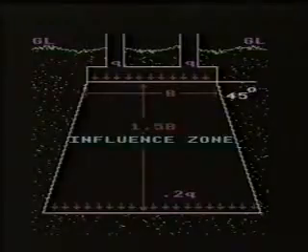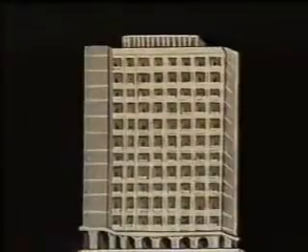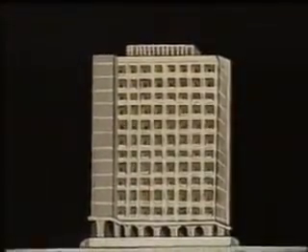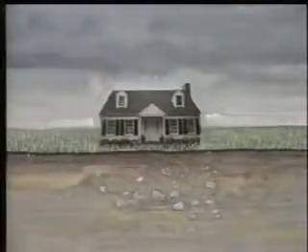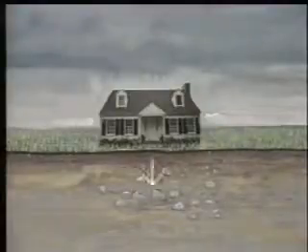Samples should be collected from the influence zone, which extends up to a depth of 1.5 times the width of foundation. For compact building sites, say up to an extent of 4,000 square meters or so, samples are collected by making boreholes, one in each corner and one at the center. For small buildings, a single borehole at the center is sufficient.